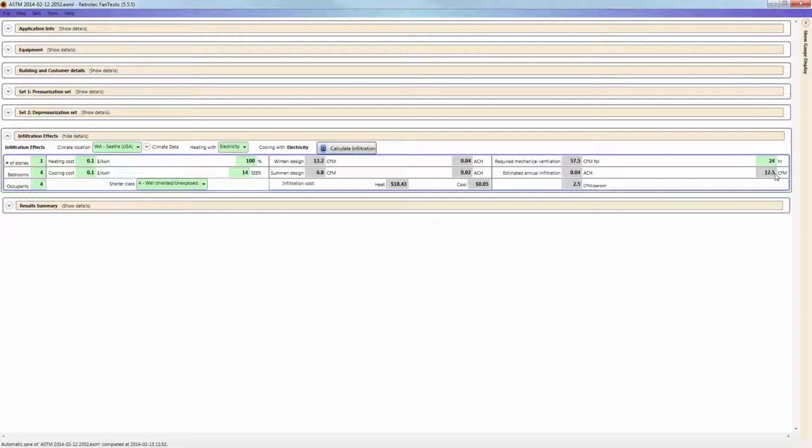If you looked it up in your table, there's a table that shows you the real factor to use. It might have been a little closer, so they're in the same ballpark. So 12.5 CFM is not really enough for people, so obviously this house is going to rely on continual ventilation from the vent from your ERV or HRV or whatever it is.